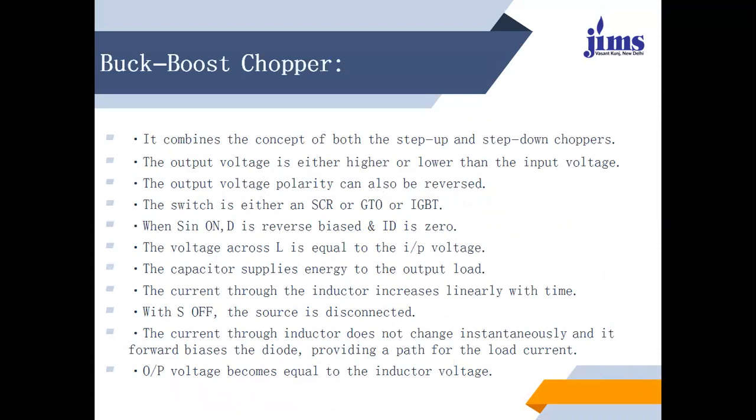Next one is the buck boost chopper. It combines the concept of both the step up and step down chopper. The output voltage is either higher or lower than the input voltage. The output voltage polarity can also be reversed. The switch is either an SCR, GTO or IGBT.